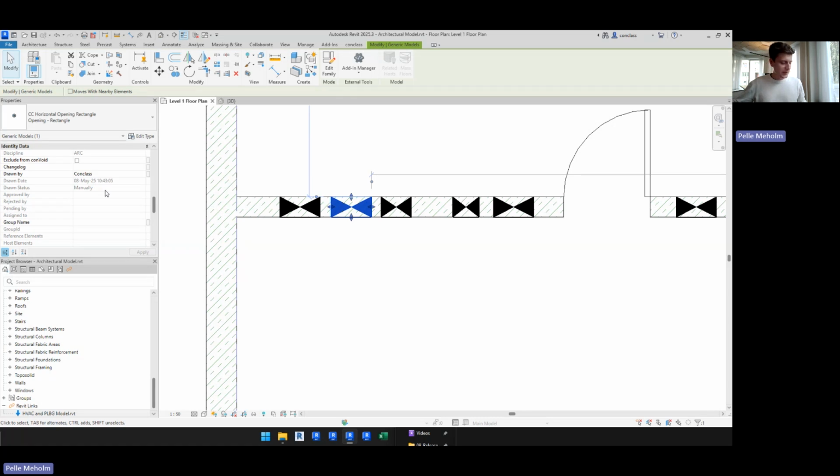So run the one filter 3 times, split up your project, or use the 3D section box and run ConVoid for level 1 to level 5, and then from level 5 to level 10, and from level 10 to level 15 to ensure the best results.